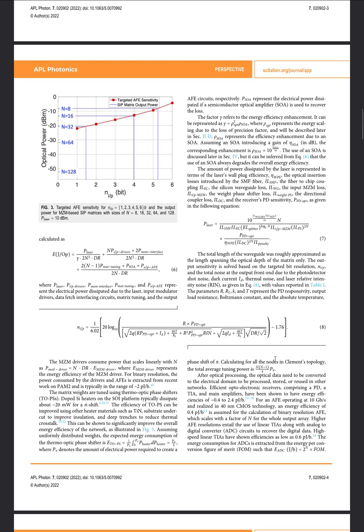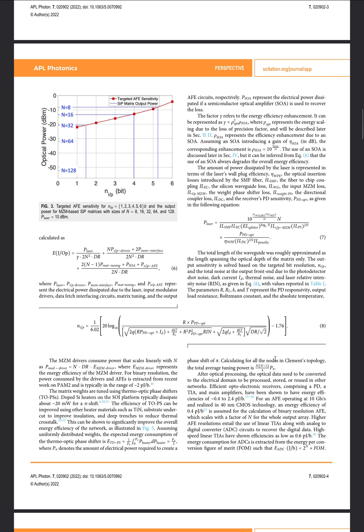However, the use of heaters is not ideal because the issue with heaters is that they continuously drain power to operate, and there is thermal crosstalk. And as we'll get into later, the solutions listed prior, unfortunately, do have drawbacks in that they cause thermal isolation and self-heating. This exacerbates self-heating, and these silicon photonics are very sensitive to heat, especially with how small they are.